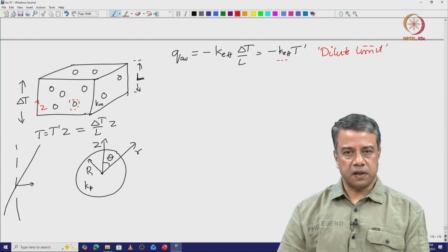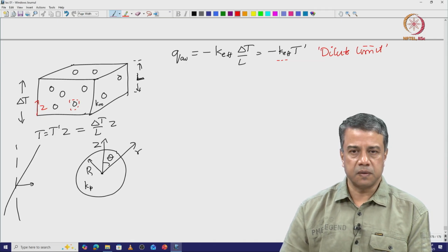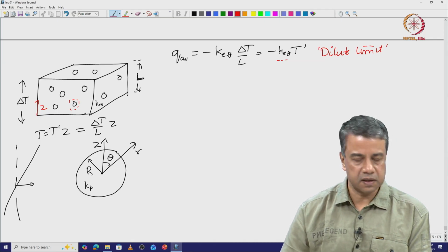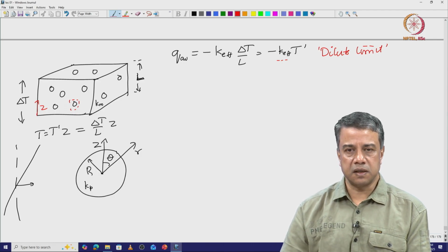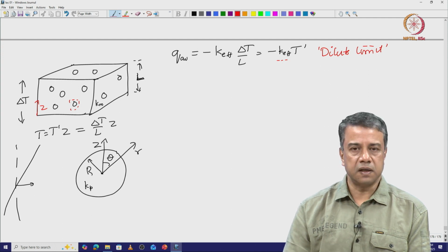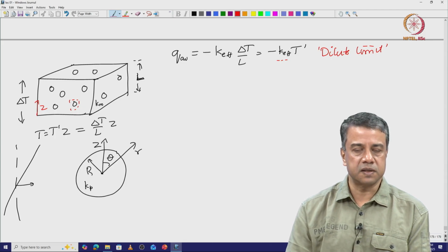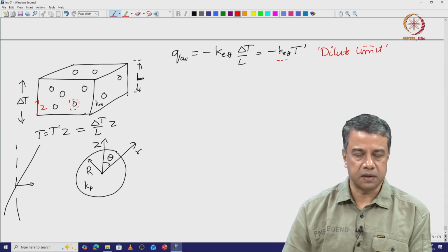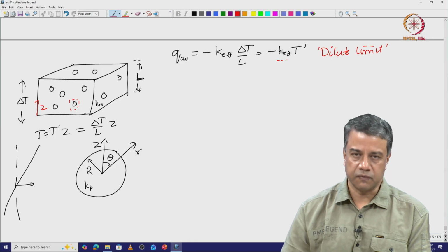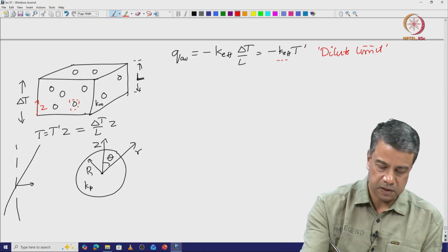where the temperature disturbance due to one particle does not affect the temperature field around another particle. So, that the particles can each be considered to be a spherical inclusion in a linear temperature gradient far from the particle, because there is no disturbance to the temperature field at this particle due to the presence of other particles. As we will see, that is valid only in the limit of small volume fraction or when the distance between the particles is much larger than the particle radius.